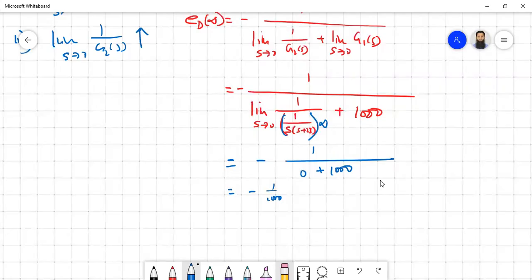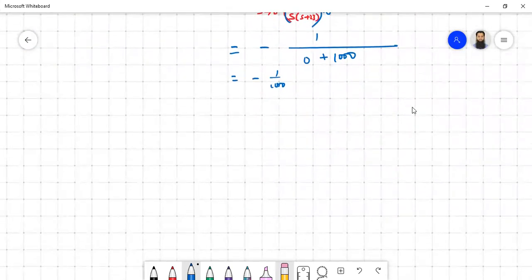So far, whatever we have discussed up to this class is basically the unity feedback system. We have derived the formula for the unity feedback system, found the static error constants, and seen how different input signals relate to these static error constants. Finally, for the unity feedback system, we also saw how to deal with disturbances and what their contribution to the steady state error is. In the next class, we will start finding the formula for the non-unity feedback system. So far everything was a unity feedback system.